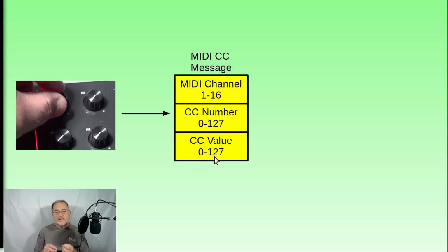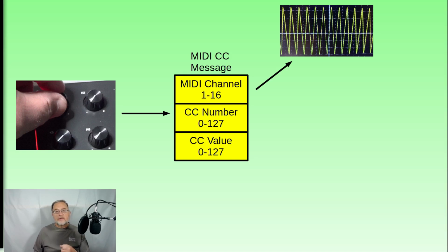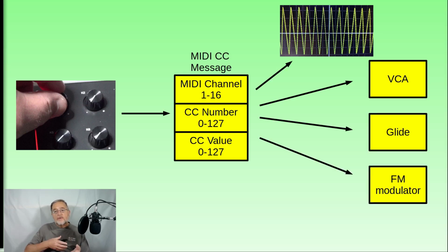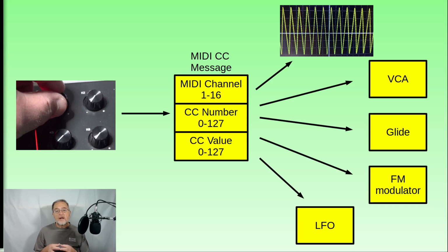Control change messages are usually created by a MIDI controller in response to the adjustment of a potentiometer. The current position of the potentiometer is provided with the last data information in the MIDI message. We can use such information in our synth to generate a corresponding control voltage that we can use for several purposes. From simply adjusting the pitch of a sound waveform to the control of various parameters in the synth, like the volume level of a VCA channel, the duration of the glide, the depth of a frequency modulation, or the frequency of an LFO.